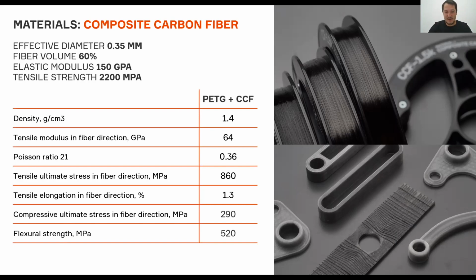As I mentioned, there is a high flow melt required for better processability. So yeah, it really makes sense to print the chopped fibers on the FDM nozzle, but on the CFC, on the composite nozzle, as for our experience, it's better to use neat grades, uninfused grades.